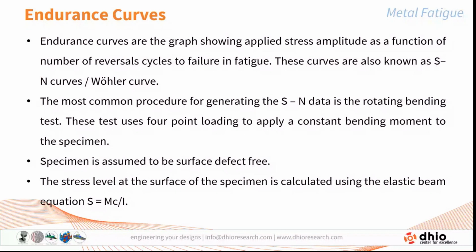And the plot of the level of stress induced in the member against the number of cycles which it can sustain is called the endurance curve or the endurance graph. Endurance curves are graphs showing the applied stress amplitude as a function of the number of reversed cycles to failure in fatigue. These curves are also known by the name of their inventor, Wöhler, and are also defined as Wöhler's curve. The most common procedure for generating the stress versus number of cycles data is the rotating bending test.